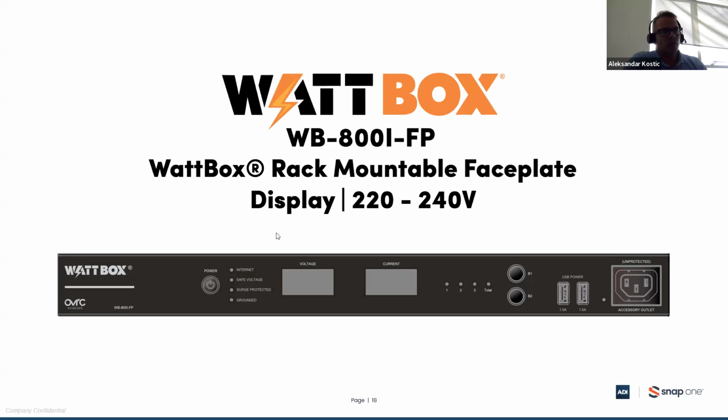So when you select, for example, WattBox number 2, and if you press and hold B1 or B2 for like 5 seconds, it will restart the WattBox. So you do not need to go back into the rack and unplug the WattBox. You can do it directly from the front side, from the faceplate itself.